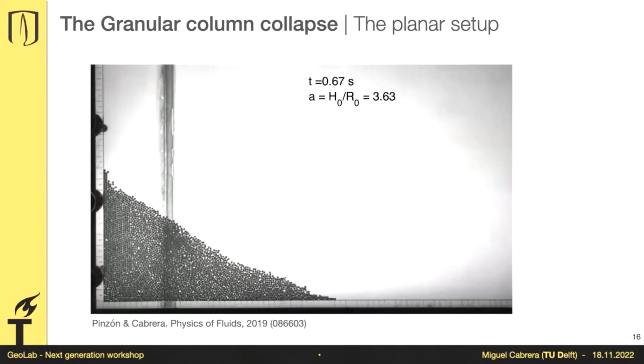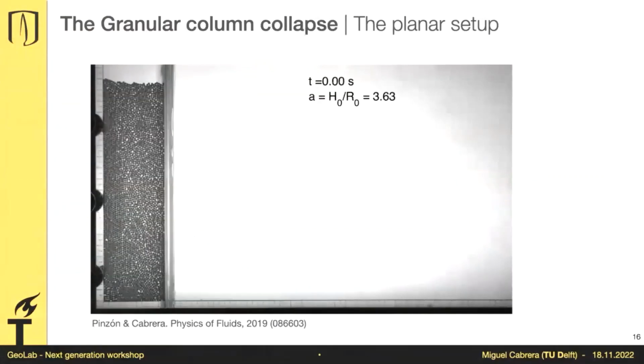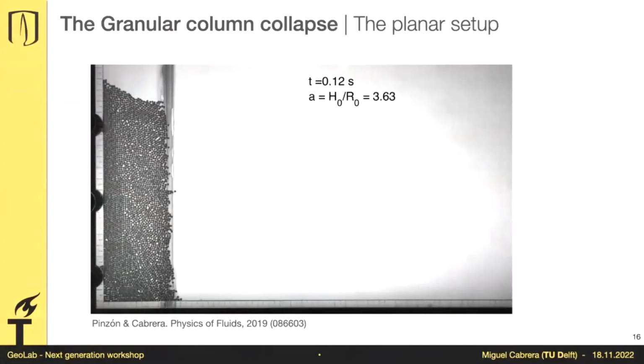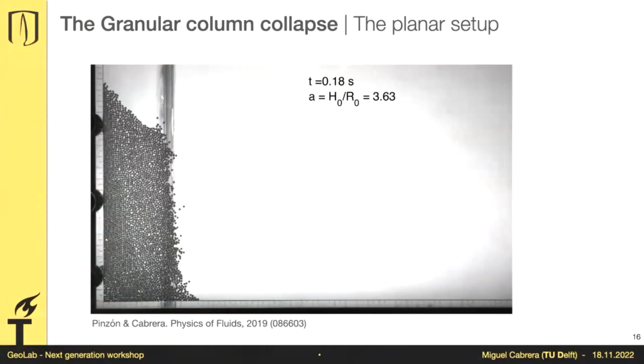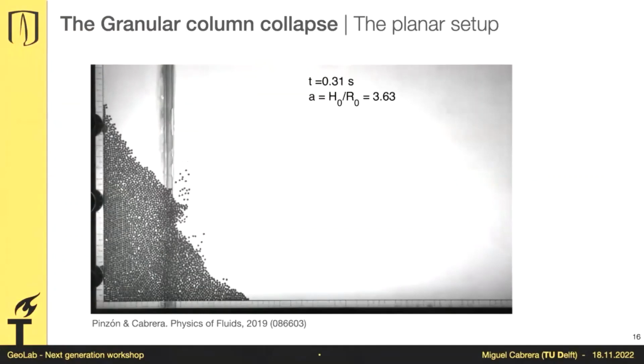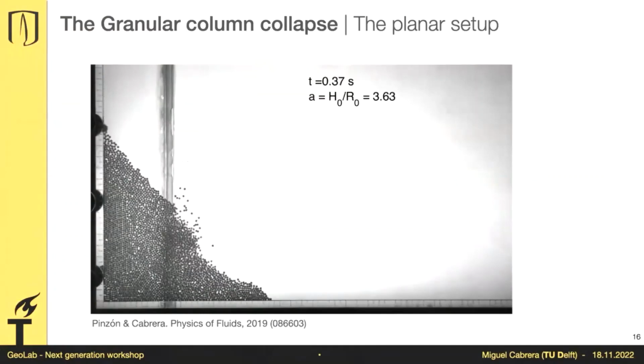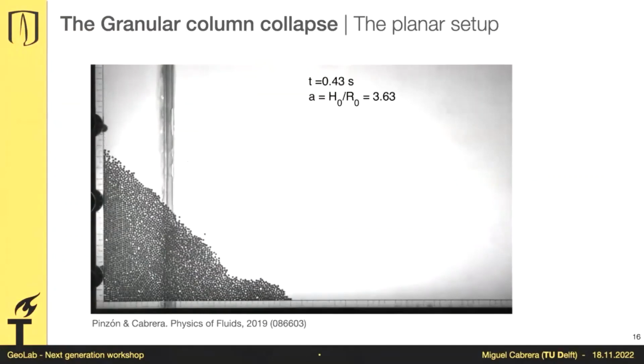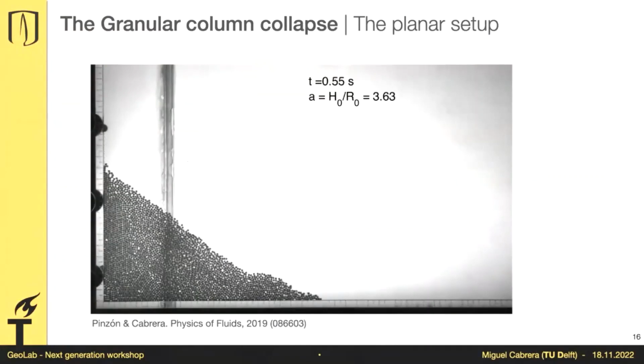Here, still we have a vertical motion, but that vertical motion rapidly transitions into a lateral motion. And that lateral motion is only possible due to dilation. Please notice that there is a wedge where you'll see more white spaces between the particles. And once they are moving, they reach this critical void ratio that we like in soil mechanics, and they come into an almost steady motion.